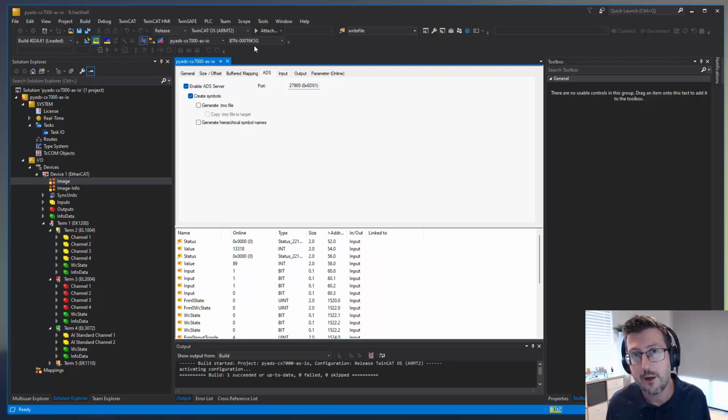What actually happens behind the scenes is it goes, hey, TwinCAT, I've got a name of a symbol. Can you resolve this into an index and offset for me? It provides that back to the software that's asked for it. And at that point, if I want to read or write, it's by index and offset. So you get this sort of few-way jump between resolving a symbol name, ultimately.